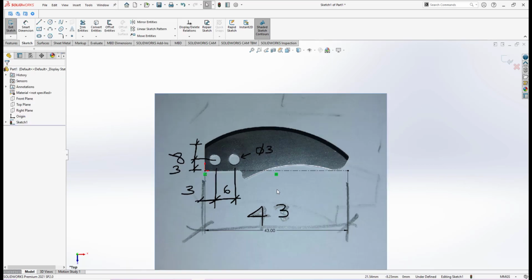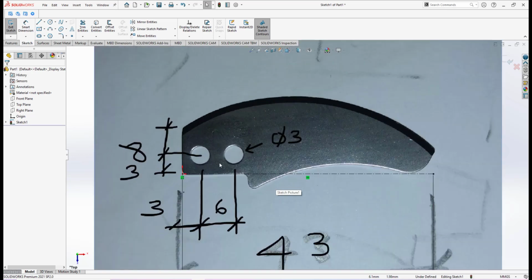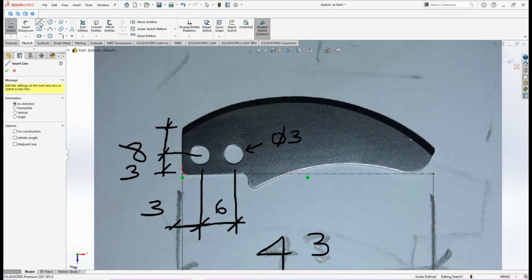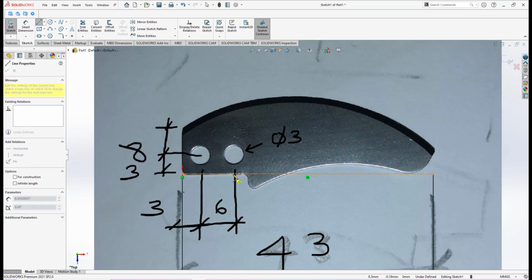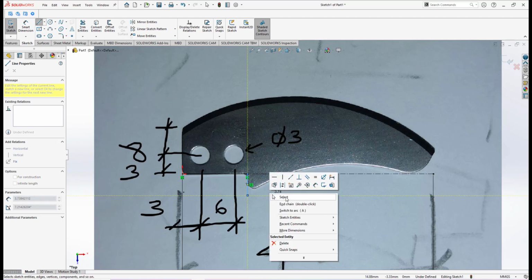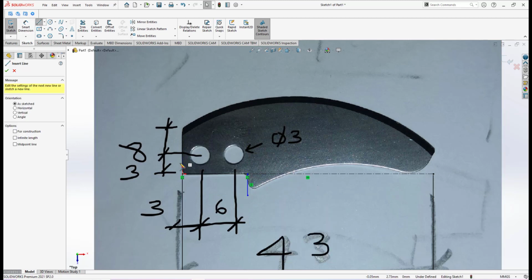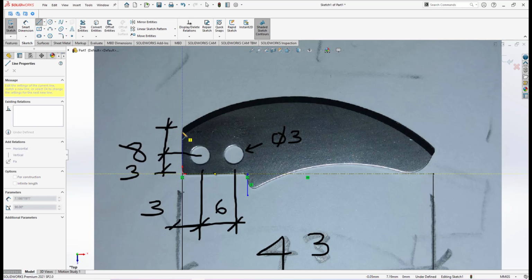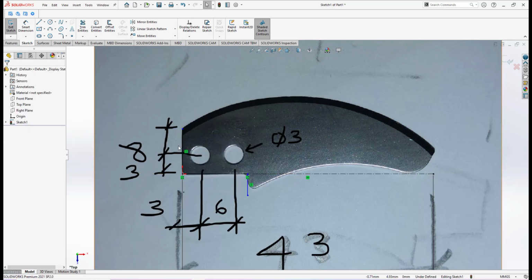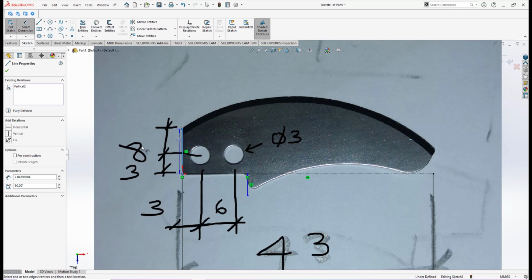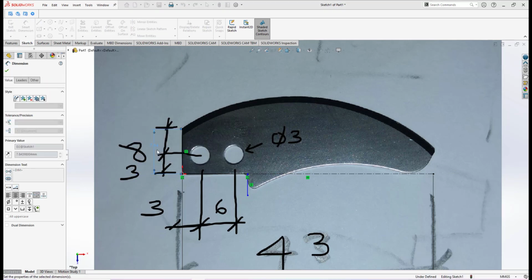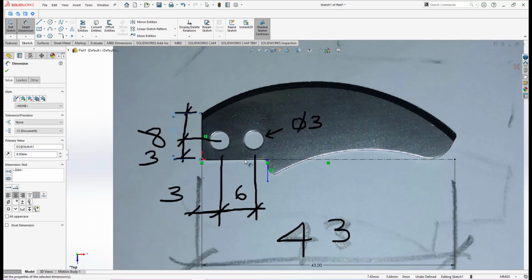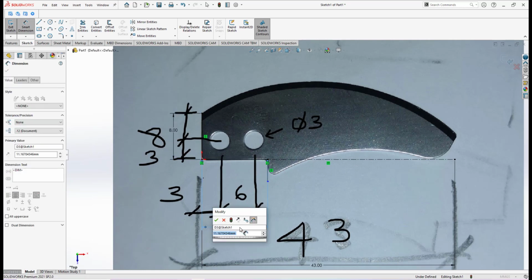Then I click OK. Then I will do tracing by creating a sketch. This is the origin point, so I will start at this origin point with a straight line here, then somewhere around here, then this is vertical. I stop somewhere at that point, and also I have this point here, where I made a vertical line at that point. Then I know the dimension here is 8, so I put a dimension of 8. And also the dimension here is about 11, so I put 11.